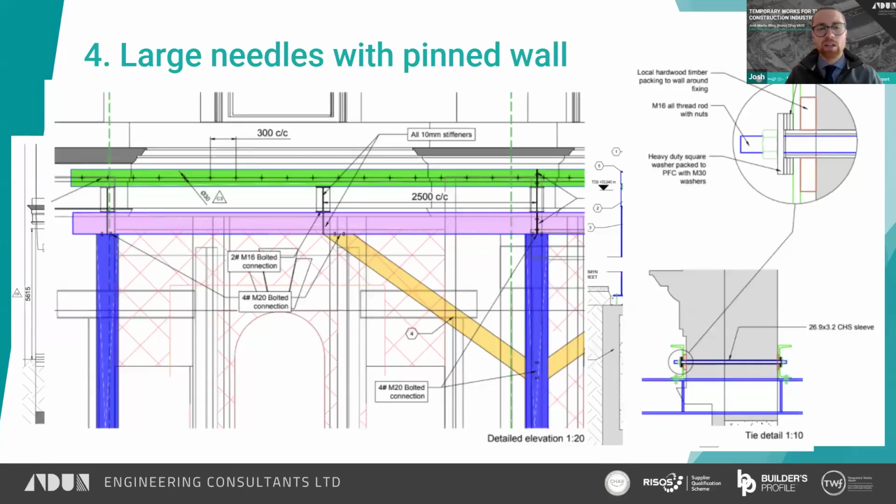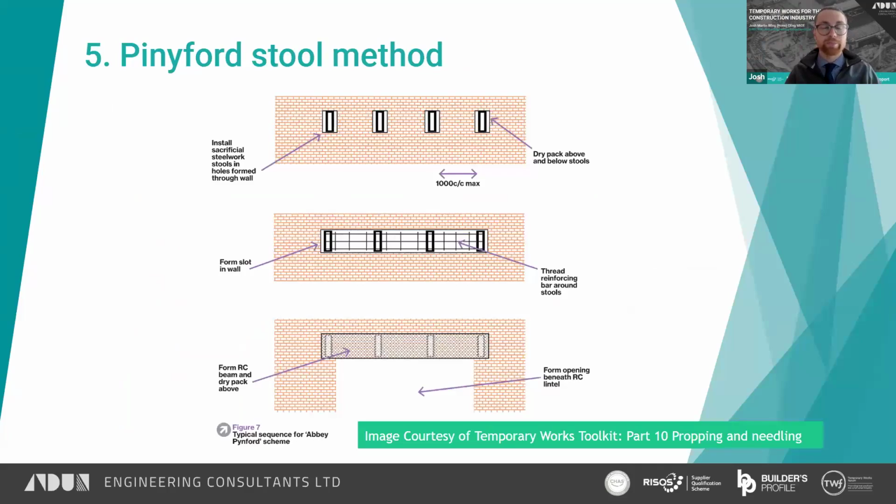And then due to the size of the loadings and the quite awkward site constraints, it was necessary to go with a bespoke fabricated solution. And this PFC pin solution also could be used to limit the amount of damage in the wall, because a more traditional approach of having needles at much more regular centres would have led to larger openings in the quite fancy stonework wall. So this is a solution which worked very well for this project. It was quite a number of constraints which led to the solution.